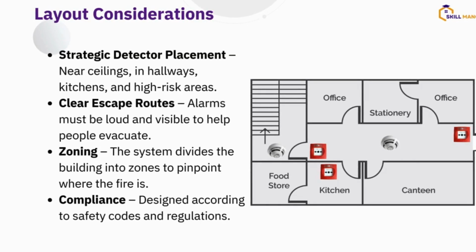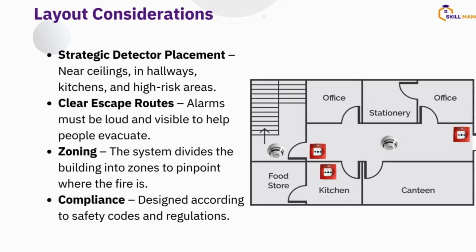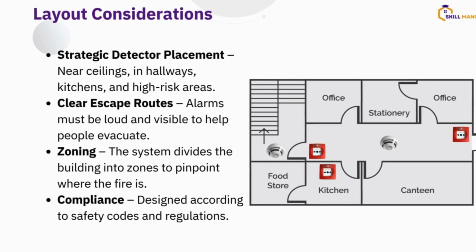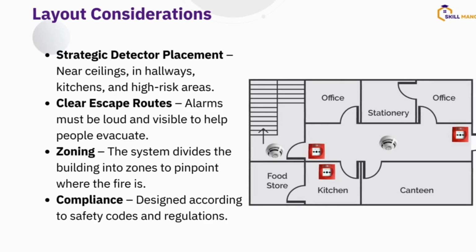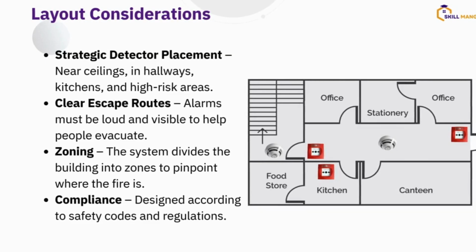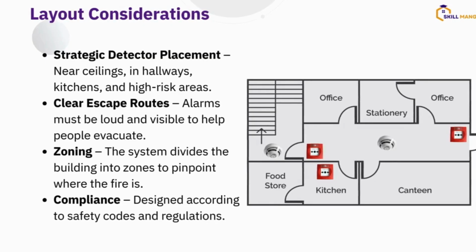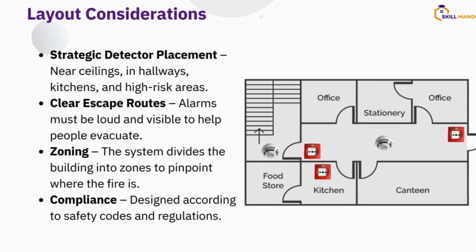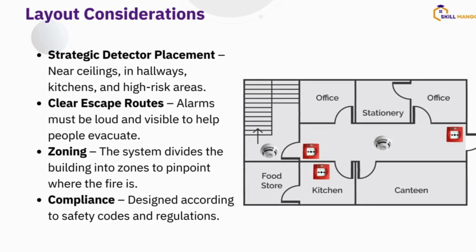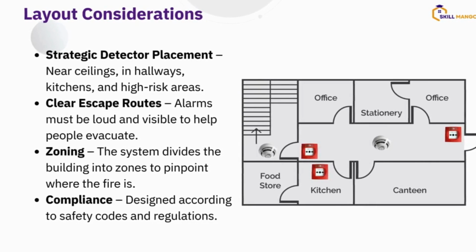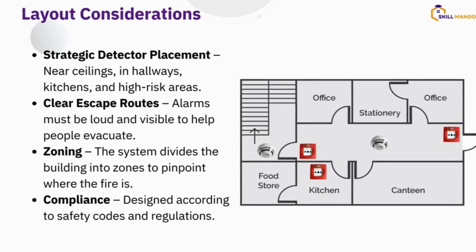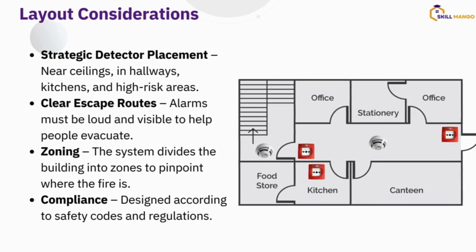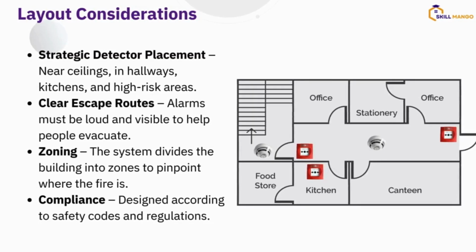And you have to look at compliance. You have to follow the state safety codes and conduct in your region to ensure that everything is intact. In some regions you have to get a muster point, you have to get an extinguisher on each of the floors, you have to get a fire blanket and put it on the floors. So check out your fire service in your region, depending on the industry you are working for, you are installing the equipment for.